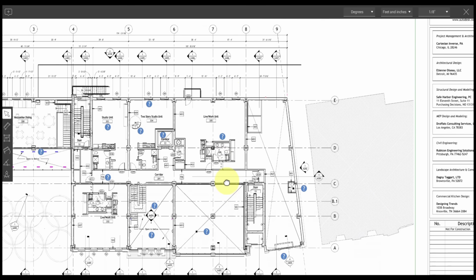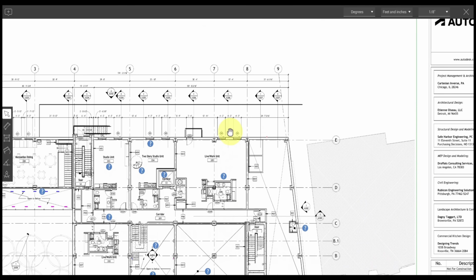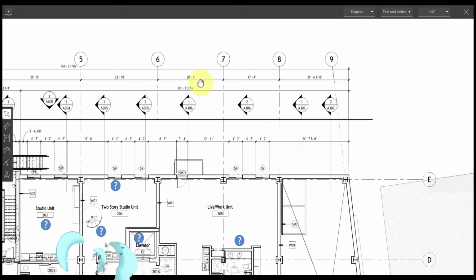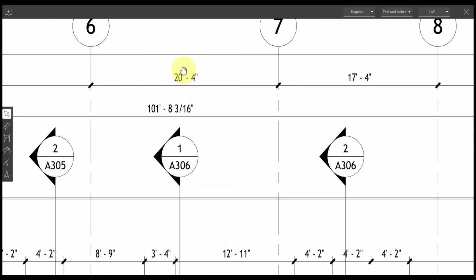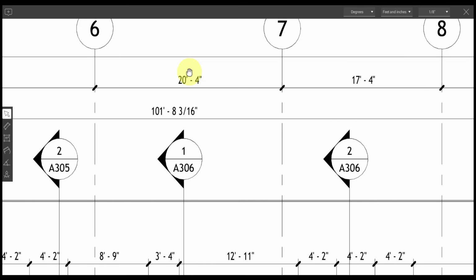One note that I want to bring up: the good thing about Revit is that if you export the sheets from Revit, the sheets are already scaled, and most PDFs come in automatically scaled, but always try to check your drawing. Just take any dimension, go to the ruler, and grab it from this corner all the way to here.